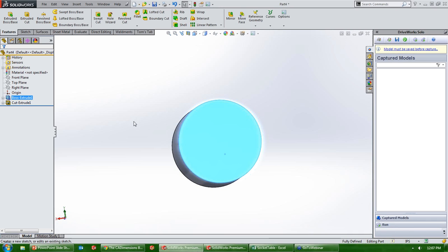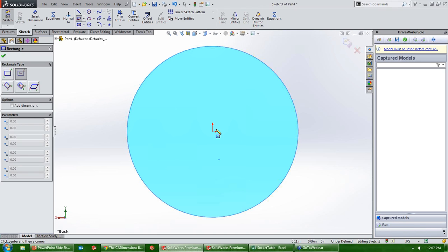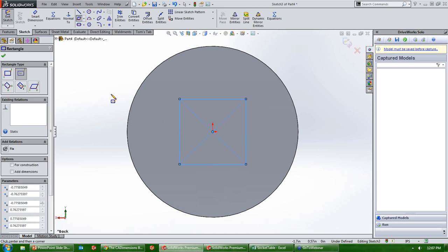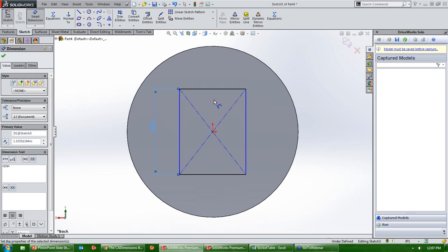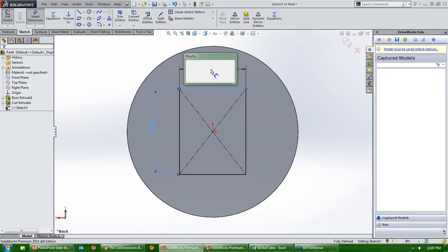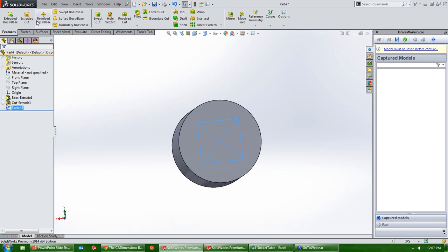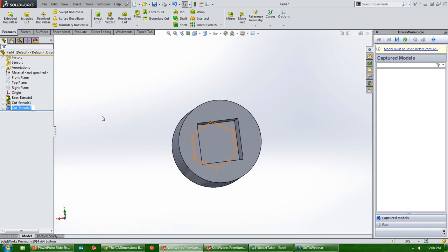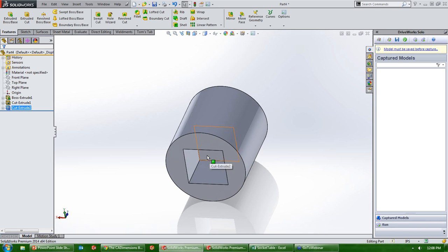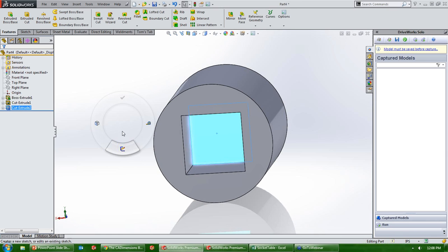All right, and then on the other side, I want a square fitting. So this is where my socket's going to connect to my actual handle. Get some dimensions on here. Looks good. One more cut. All right, and now all these dimensions that I'm actually cutting and extruding are recorded in SolidWorks as the dimension. So later on we can drive those using DriveWorks.